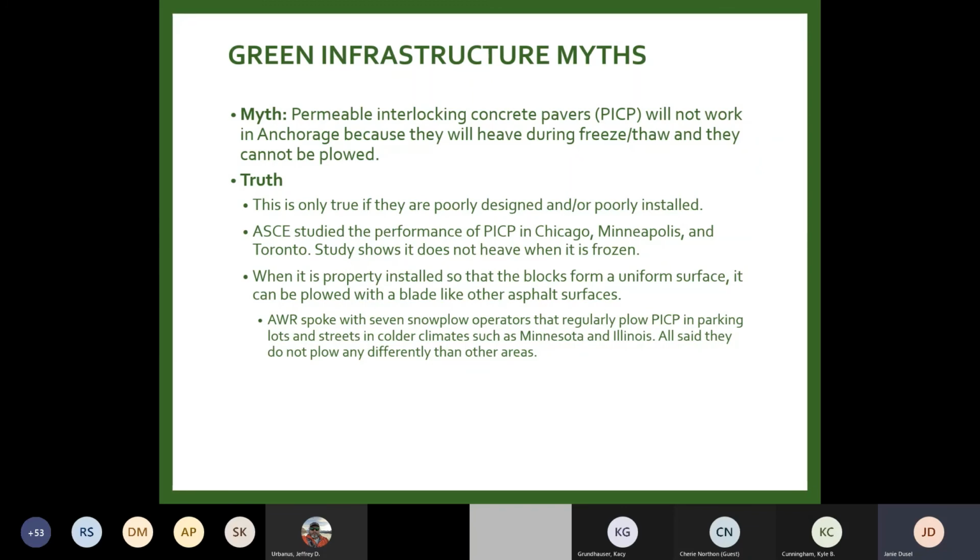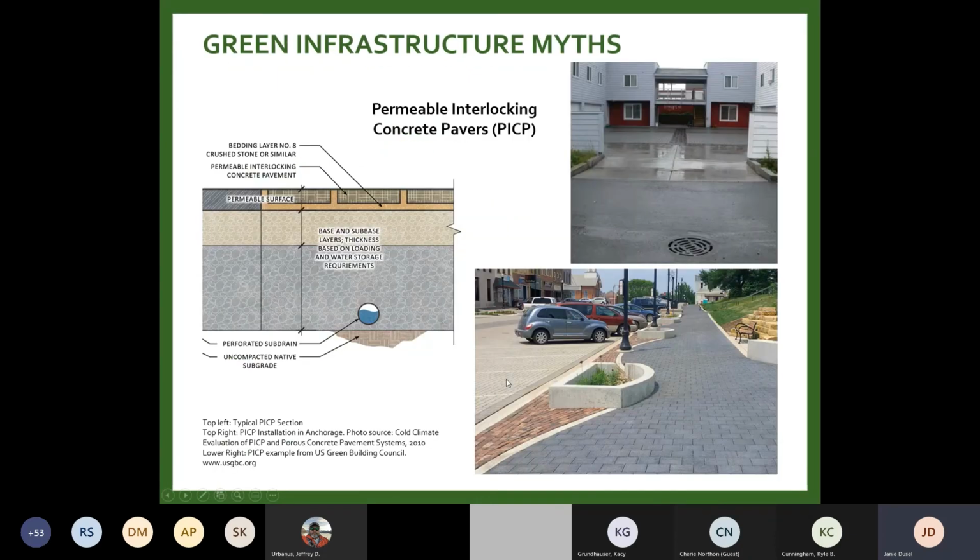So one of them specifically, we had a conversation with about the fact that maintenance issues come up when it's poor construction. So he specifically told us, if you look at these examples, there's no edges of the actual pavers sticking up, right? Even though this is sloped, it's definitely sloped to this curb line. It's all in the same plane, right? You don't have jagged edges sticking up.